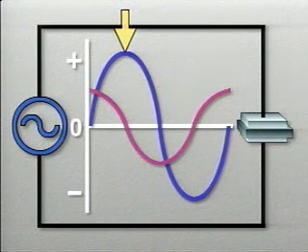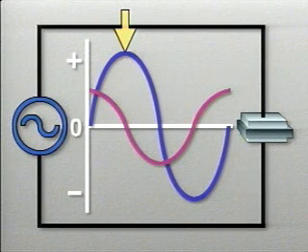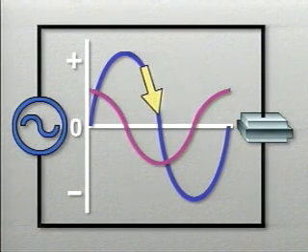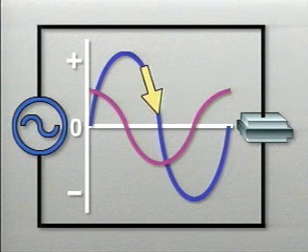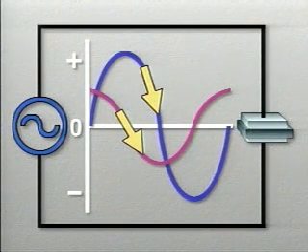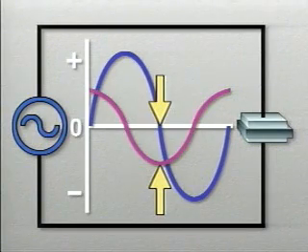The voltage across the capacitor is equal to the source voltage, but it opposes the source voltage. The two voltages have the effect of canceling each other out, so there is no current flow. Current is at zero. When the source voltage passes its positive peak, the capacitor starts to discharge. Discharging is the reverse of charging. Electrons leave the negatively charged plate and flow onto the positively charged plate. Current flow reverses direction. When the source voltage reaches zero, current is at its peak negative value.